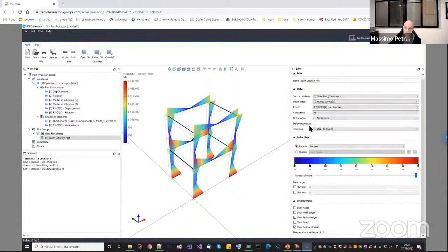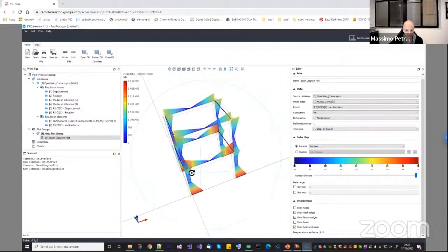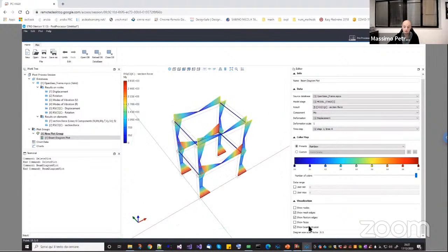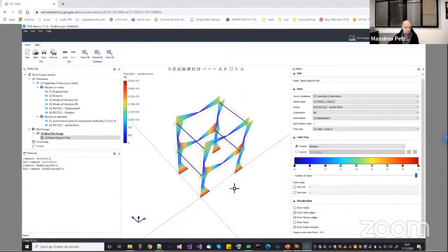Instead, in this way, since you have all the displacements for every mode, you can compute the drift for every mode and then do the CQC combination on the drifts, for example. So of course, there is more freedom. As I said, don't worry about the Python scripting because I know that not all of you are experts in Python. And of course, we will provide a user interface for doing the standard combinations, okay? So I just wanted to take this occasion to show you the great new features of STKO in version 2.0, okay? And of course, you can do many more things with this kind of post-processing.